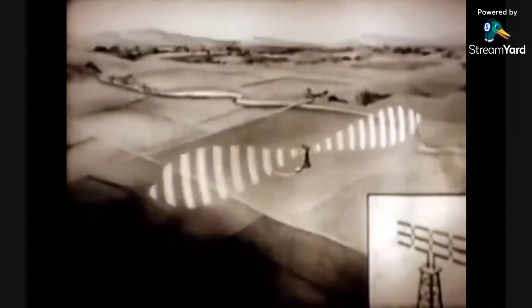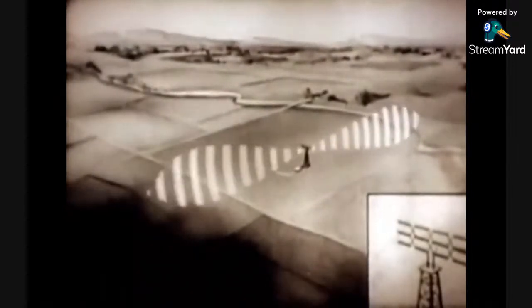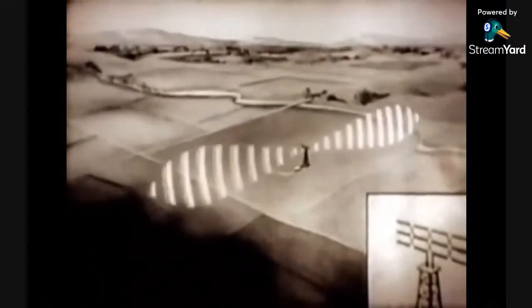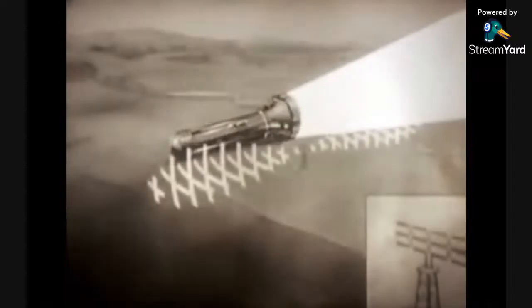It is these waves which cancel some of the radiation from the first level of elements. The half-wavelength spacing between element levels makes possible this cancellation. As you see, the effect of condensing the wave pattern by using several levels of elements serves to increase the energy in the desired directions and gives greater gain to the beam. It's like focusing a flashlight. Adjust the lens and the beam is concentrated.